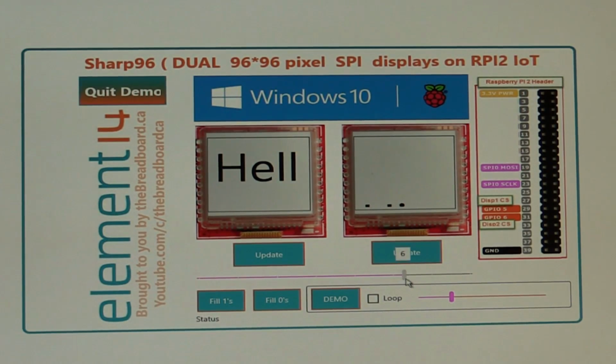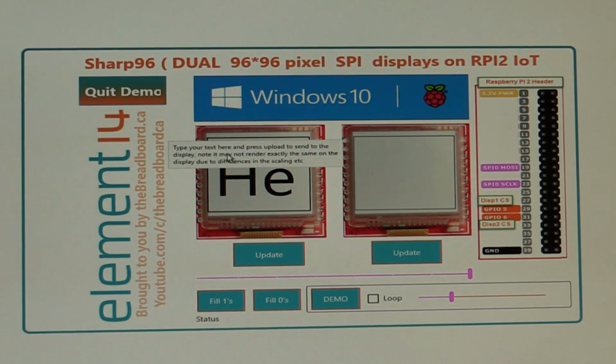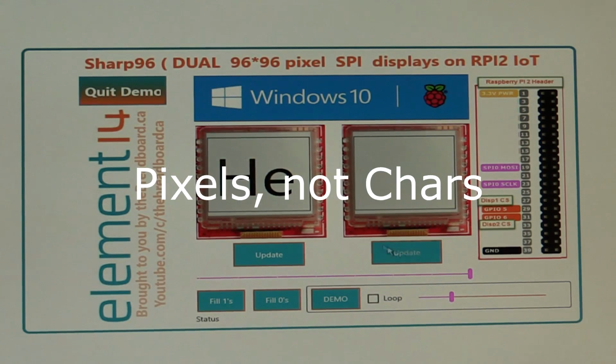But whatever font size you pick here, up to 8, it will actually output the representative scale. So it's an 8 by 6 font, 6 characters wide, 8 characters high. If you're doing 8 as a font size, then it's going to be outputting 6 times 8, so 48 pixels wide and 64 pixels down, 8 times 8 is 64, on the screen. So that's pretty cool.